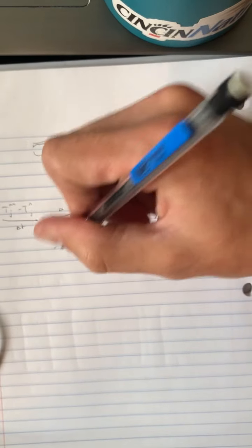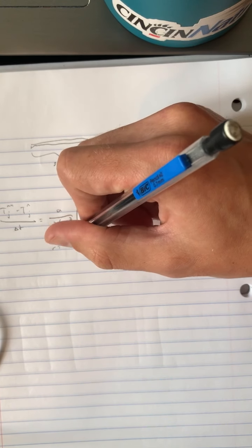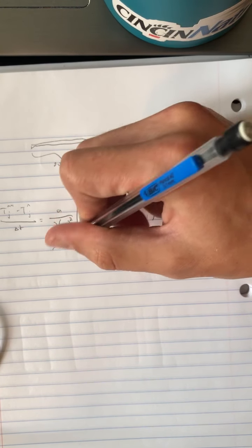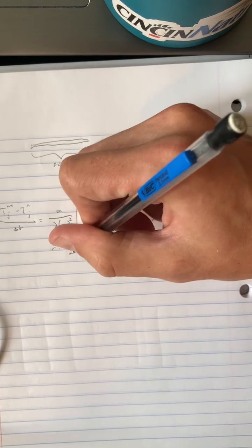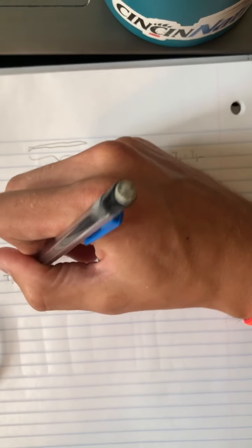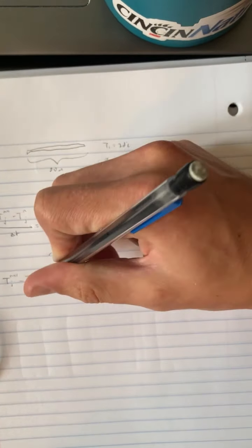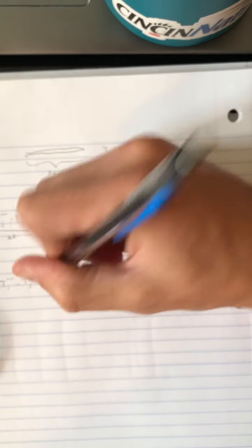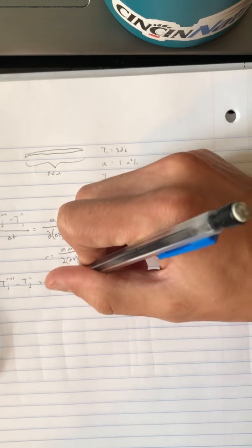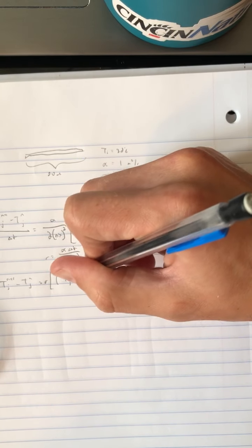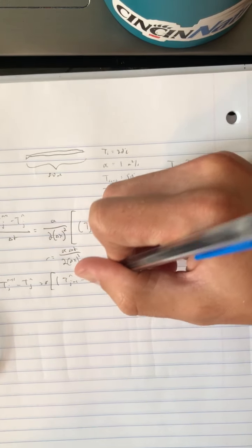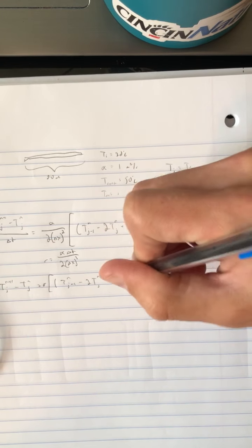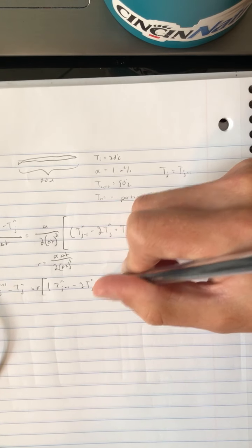If we use our r value as equal to the thermal diffusivity times change in time over 2 times change in x direction squared, we will get a simplified version of the equation that we can simplify further to this. We want to get all of the values at n, which will be the current time, on one side.